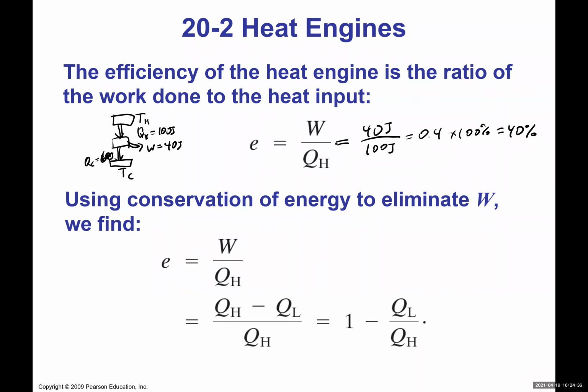So 40% efficiency means that this engine can extract 40% of any type of energy that enters the engine into useful work. But 60% of it is exhausted. Roughly this 40% can even be considered an efficient engine. Generally the efficiency is very low, for example cars. The typical car has an efficiency of maybe 20%, 25%, depending on what car you are talking about. But generally 30-40% can be considered a relatively good, efficient engine.